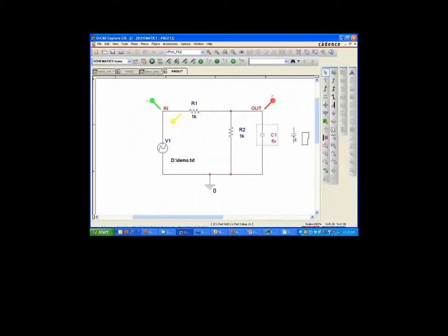For example, like this. What if I, let me just do this. By the way, you can pull a component out of here if you hold down the Alt key and drag away. That's the Alt key, and drag your part away. You can rip it up from the traces. What happens if I want to put that back in there?